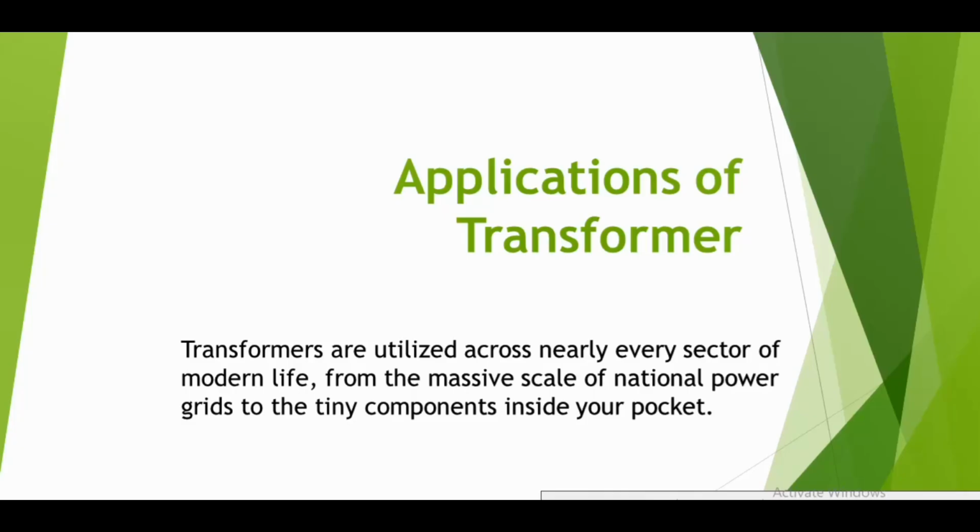Correspondingly, the loss of power in transmission is small. So the voltage at the electricity generation plant is stepped up to say 66 kV and fed to the transmission lines. In a town or city, the voltage is stepped down to the required value such as 220 volt.